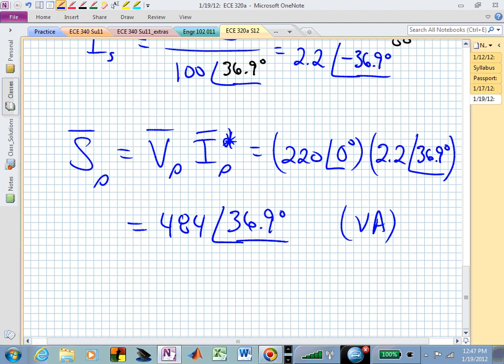The current relative to the voltage angle, I'm sorry, you can't see this on the audio, but you can see it in the classroom. Our voltage angle was here, wasn't it? At 0 degrees, horizontal. Where was our current angle? Minus 36.9. Which was leading the other? Or what was the current doing relative to the voltage? It's lagging. It's behind. So we had a lagging current.